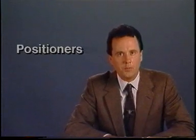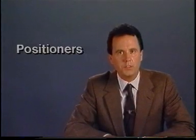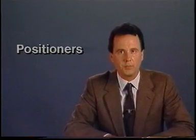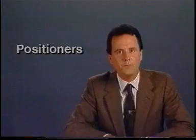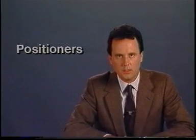Positioners are another loop component that you'll often encounter as you work with control loops. Positioners are traditionally used in many ways: to overcome valve friction, to set valve position in split-ranging applications, to position piston actuators, to provide for a more accurate reading of valve position, and for altering valve characteristics. Positioners can also be used to provide a dynamic effect on loop stability.